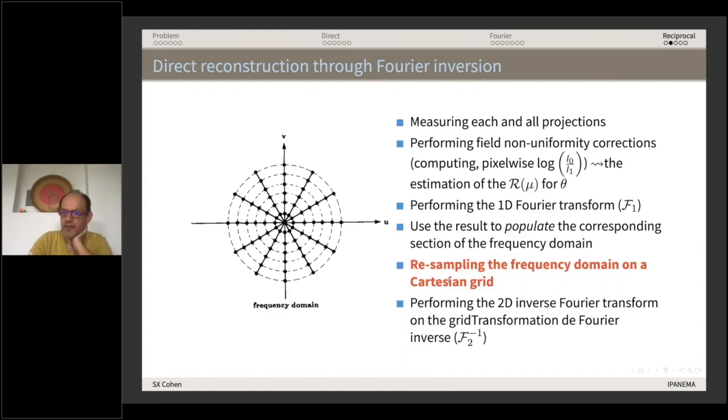The thing which is really tricky in this case is this resampling, because the relationship between the Fourier domain, the frequency domain, and the space domain or the time domain is quite complex. When I'm doing an approximation, for example approximating a point here, often I would tend to approximate it by using just the neighbors. So I'm doing something very local for the interpolation. What is local in one domain is diffused over all the dual domain.